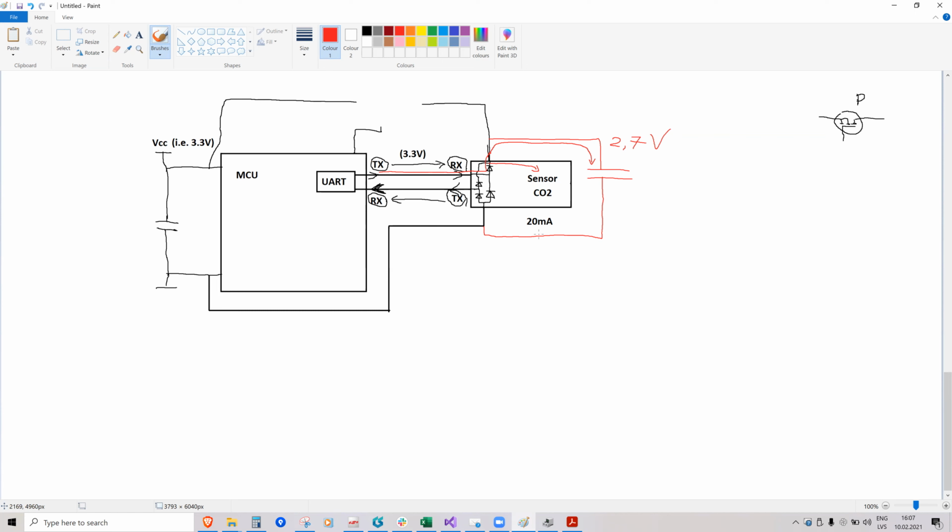And I have seen this oftentimes. For example, a person creates a device which connects to a computer, and they switch off the device with a switch, but it doesn't work because the device keeps working. In that case, the computer supplies the microcontroller through the data lines, its capacitor charges up, and it just starts working, right? So this is a common problem.